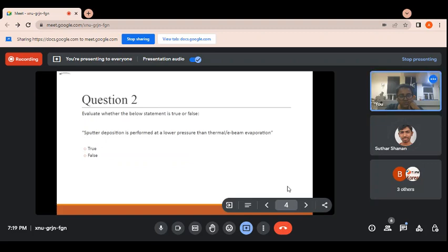Yes. When we go for thermal evaporation deposition, at that time also we use some 10 to the power minus 6 millibar pressure. So we need a constant pressure for uniform deposition. And for E-beam, I think we also need control. You have told me earlier, the total environment we need.